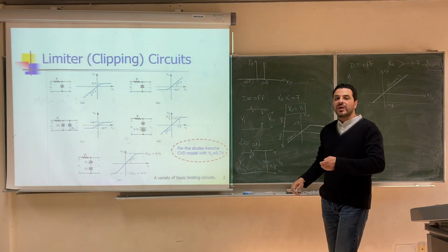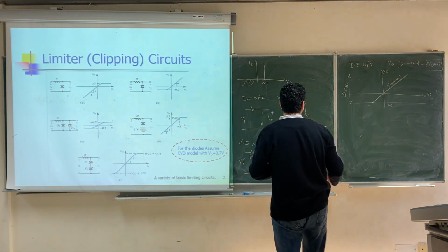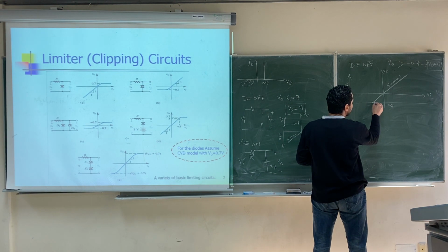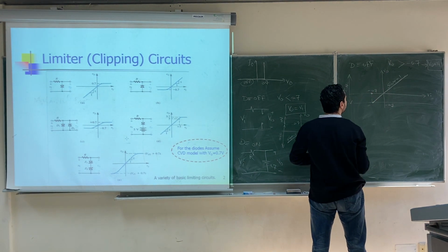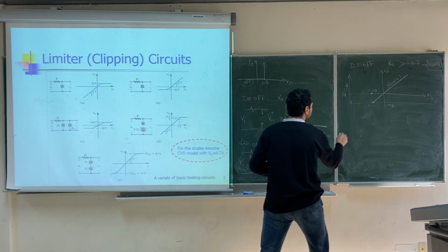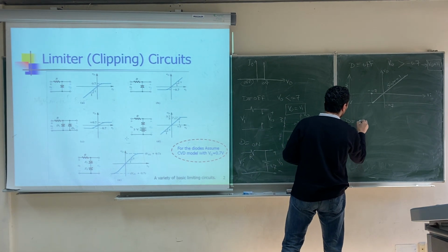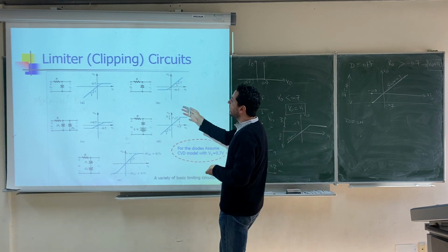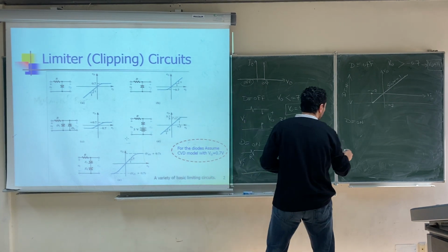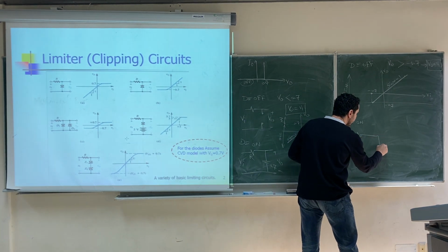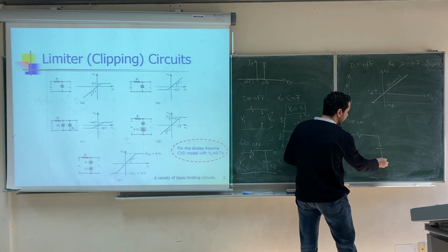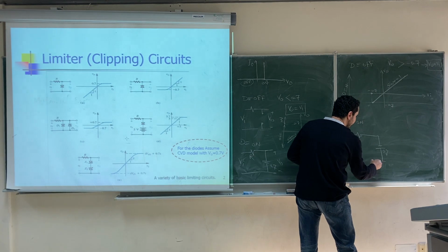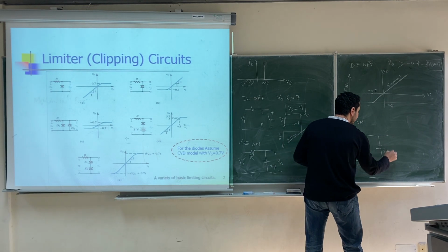On the other hand, when the diode is on, of course, if this is negative 0.7 V output, then this will be negative 0.7 V input. When the diode is on, what will happen? It will operate as a battery. The direction of the battery will be in this direction, right? Negative up, positive down. And this battery has a value of 0.7. This is the output.